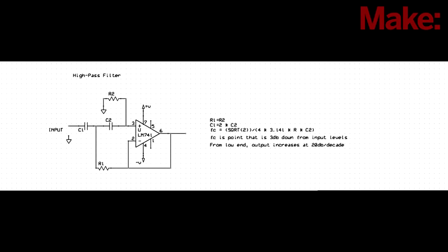The formula is exactly the same, however, and the frequency, your critical frequency, if you use the same components from the low-pass filter, that same frequency would now be your critical frequency for the high-pass filter, except everything above it would be passed equally as well.